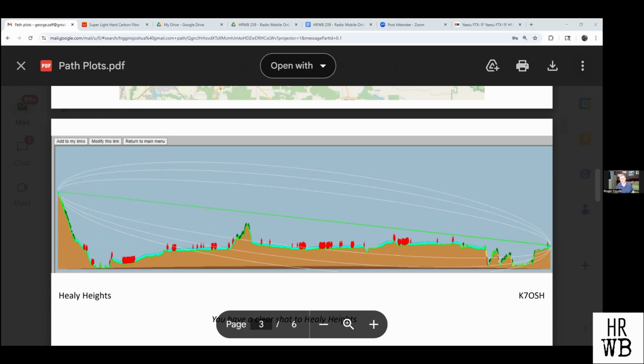of the green line. So this is a simplification to reduce the amount of calculation, and it's fair to do that, because most of the time the obstruction takes over when you are away from the first Fresnel zone. So in this case, you have a line of sight with a little loss of penetration, but you don't have what we call the full line of sight, because if there were no obstruction at all, we would say it's a free space situation.